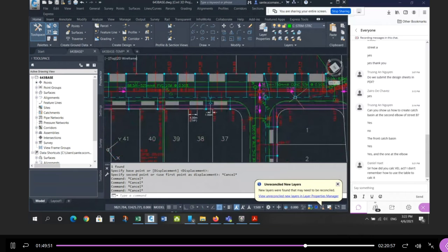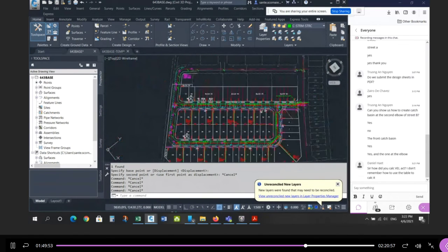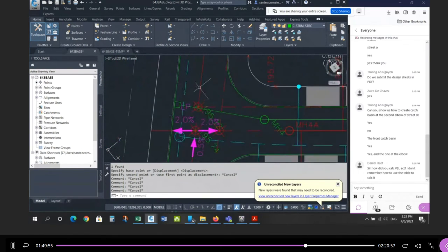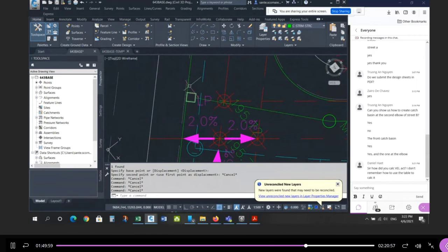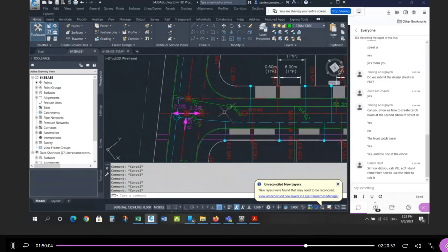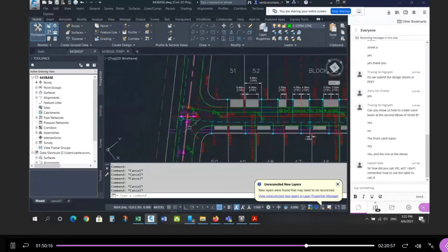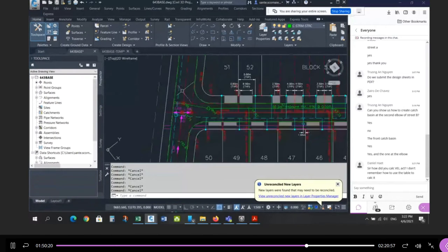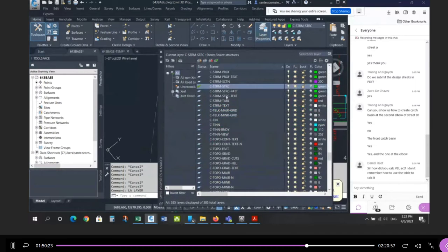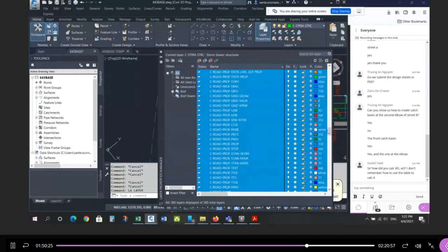Because the catch basin lead had to cross the road and connect to the manhole. Talking about this one? Yeah. This one? Yeah, that one. So I know there's a low point here on this gutter, right? So I have to connect this catch basin to a sewer, and this is the closest sewer. Yeah, good. So we have to draw it, and so why is it not placed on street A? Would it be closer? Because there's no sewer on street B. Yep. So remember your drainage areas. Even your drainage areas indicate this much.